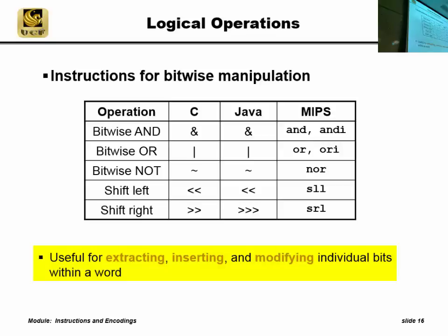Let's show you how we can extract and modify bits. This is very important. If you're making a sensor, it has certain bits come in. Each one of these bit fields, just like the instructions we saw, has a different meaning. One is the sensor value, another is a control flag that says if the data is valid or not valid. You have to go and extract those, because your job is, you work for Harris, you're an electrical engineer, you've got an antenna and it's sending this data in, and you have to pull out that field that's the data that you want. We can use these instructions.